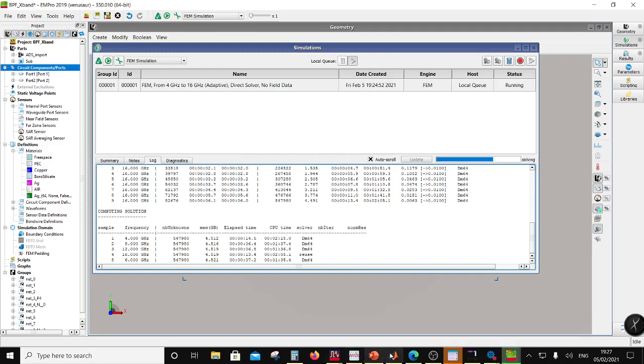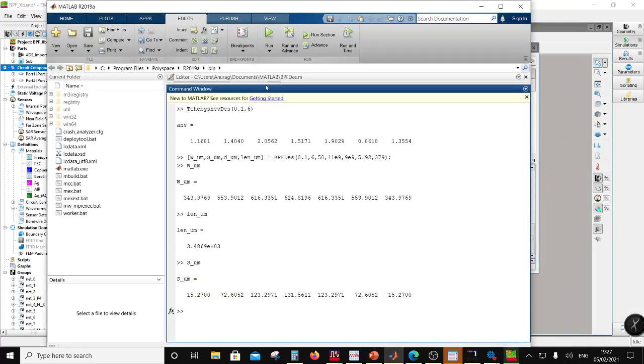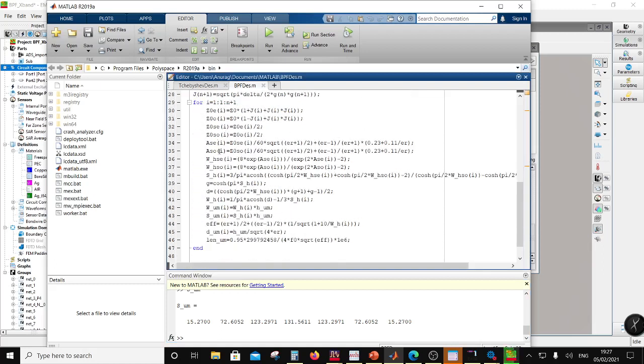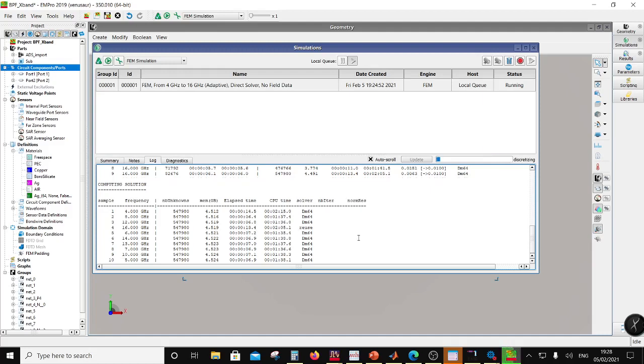And by the way, in this algorithm, usually people refer to charts for computing the width and the spacing. While over here, I have the formulae to compute the width and the spacing based on even odd impedance pairs. I use the same formula in the coupler design also, right? So the same formulas I'm using here. There's no change here. Okay, we'll be done soon.